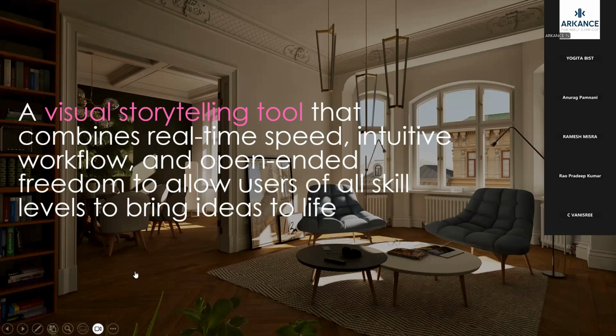The major aspect is that if I use Revit as one of my base platforms, Twinmotion has a direct connection with Revit. If I set my location, time, and zones within Revit itself, I will get the weather station data as well.